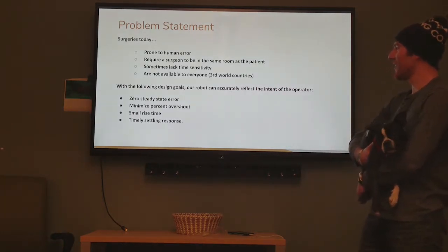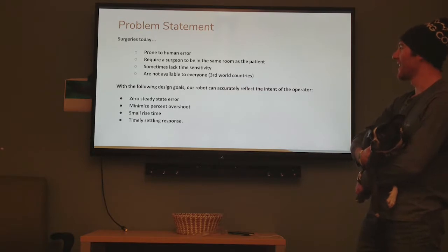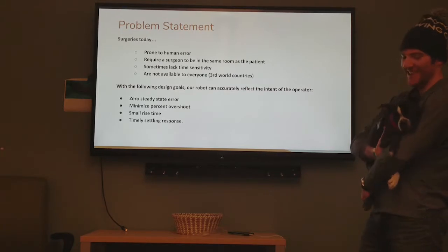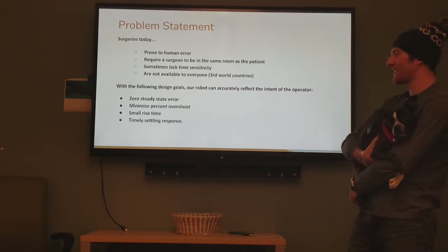In order to have a robot that can accurately reflect the intent of the operator, we thought we needed 0 steady state error, 0% overshoot, and a small rise and settle time.